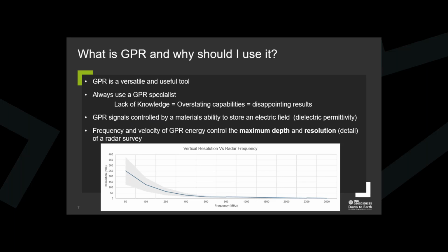We typically use a multi-channel GPR system coupled to 3 or 4 antenna with frequencies of between 400 megahertz and 2000 megahertz, which allows us to detect fine structure within the pavement while simultaneously seeing down into the subgrade and natural formations beneath the road, all in a single pass of the vehicle.